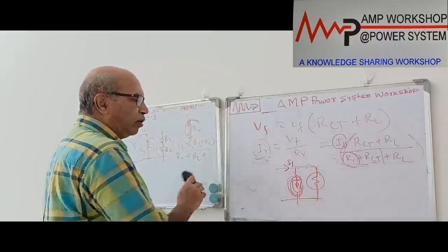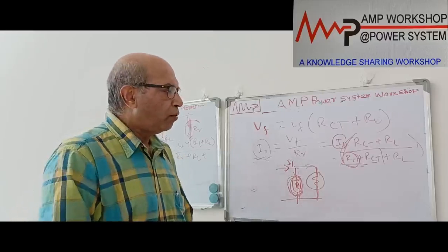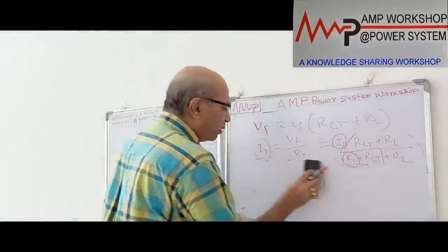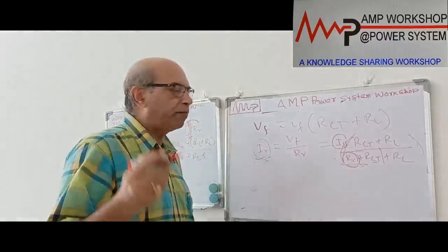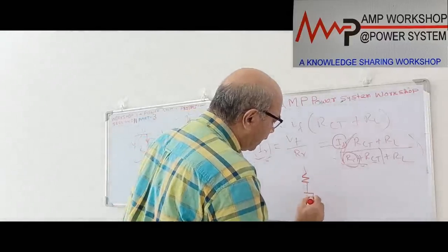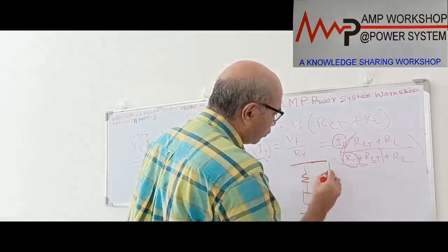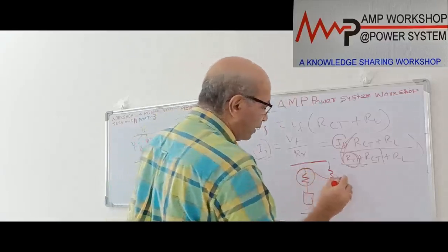So that resistance, when we do it in the low impedance circuit also, to get better stability we can include some stabilizing resistance. We call it stabilizing resistance, which will stabilize the operation. That is, on this route we put some additional resistance, and then this relay will be connected over here on this path, and then this is your CT route. Okay, this is the CT route. So this resistance we call stabilizing resistance.